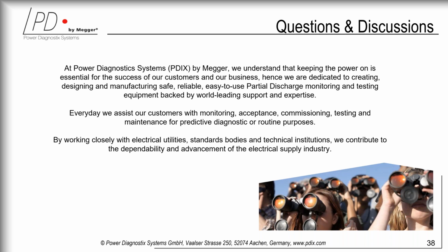With the HFCT, you have the galvanic separation of the output from the input. Some customers prefer to have this galvanic separation here on the PD output, and for that reason, you can decide at site, by opening the lid of the box, which kind of decoupling method you choose. There's a switch, a jumper on the box, and you can switch between two different modes.